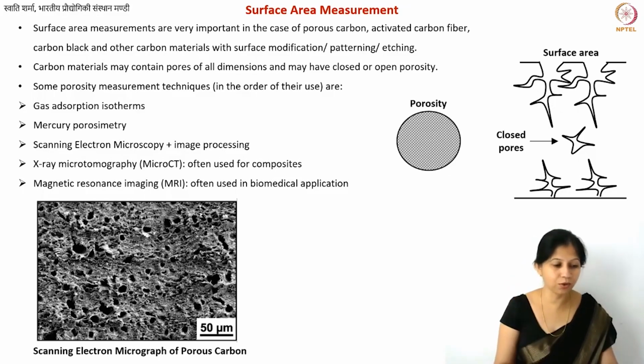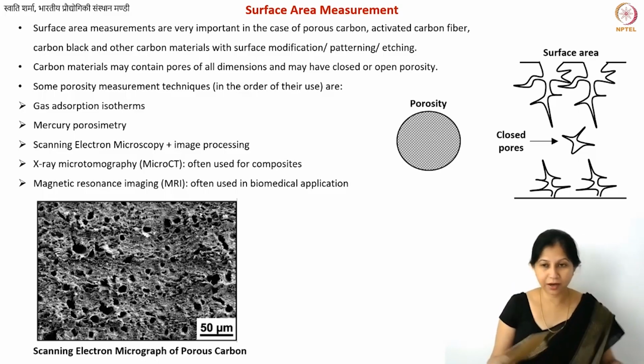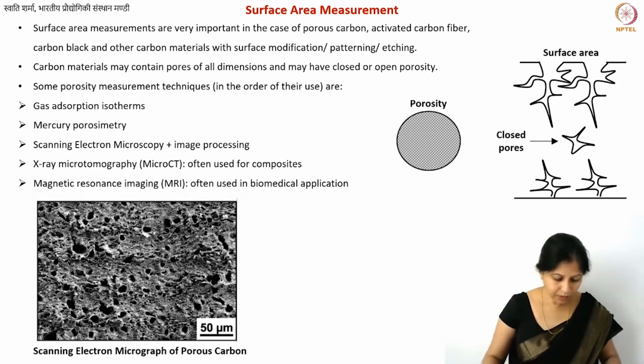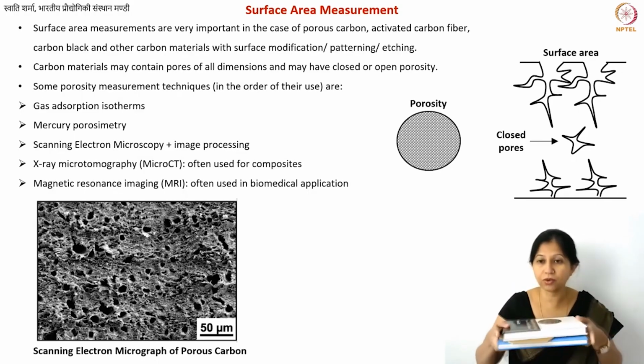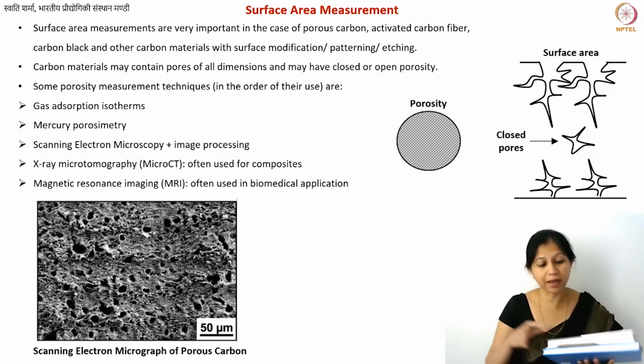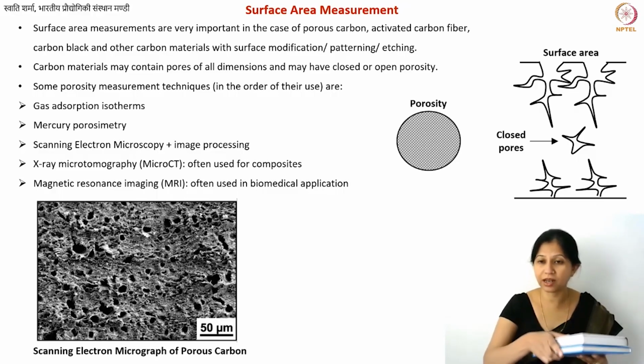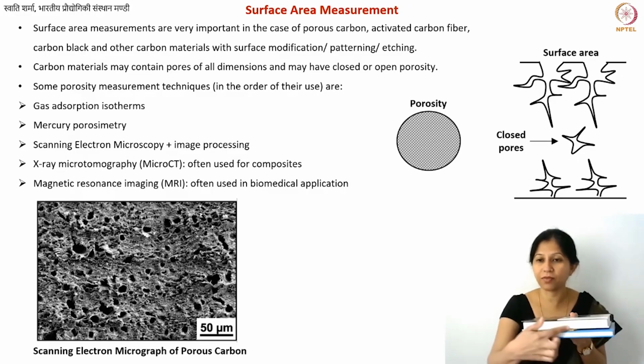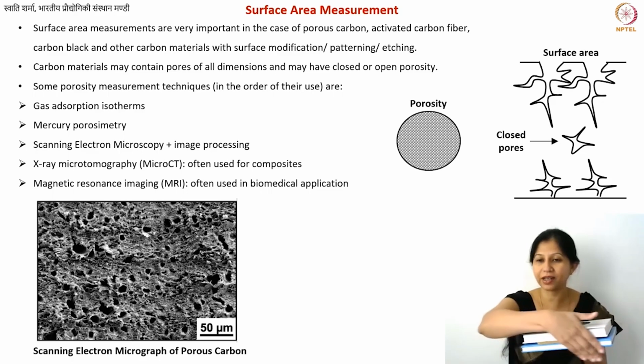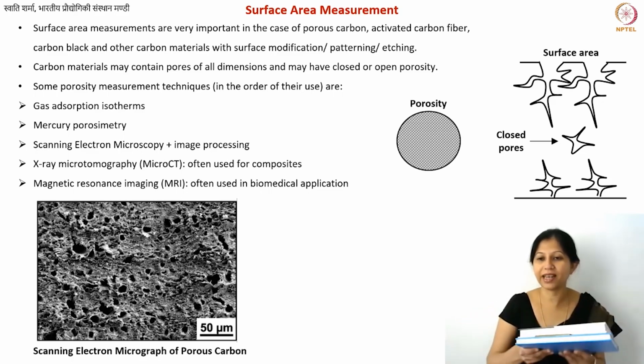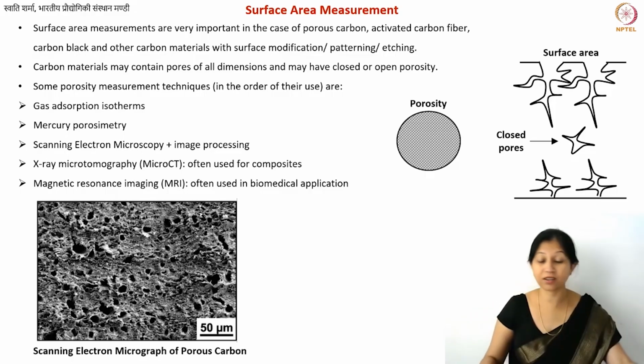So what you can do is take two structures, for example some rigid material, for example a silicon wafer. You can take two silicon wafers and sandwich your thin film between them. Then you can cut it with a diamond saw, and then take the cross-sectional image. So this is a little trick you can use.